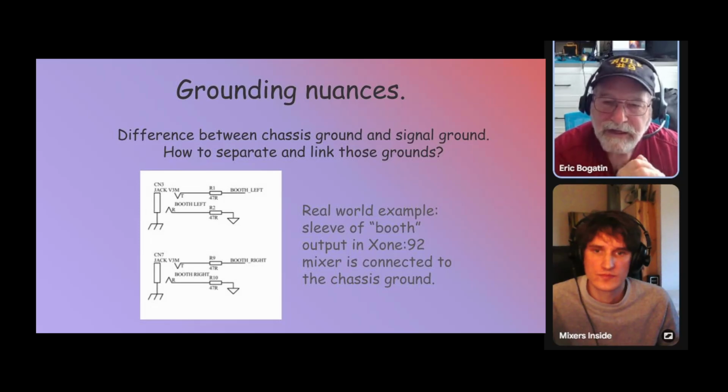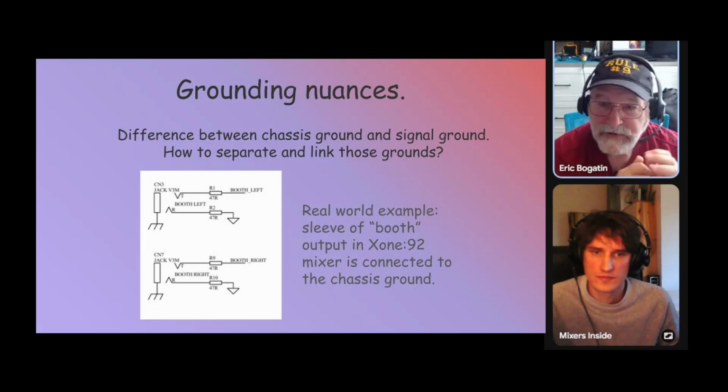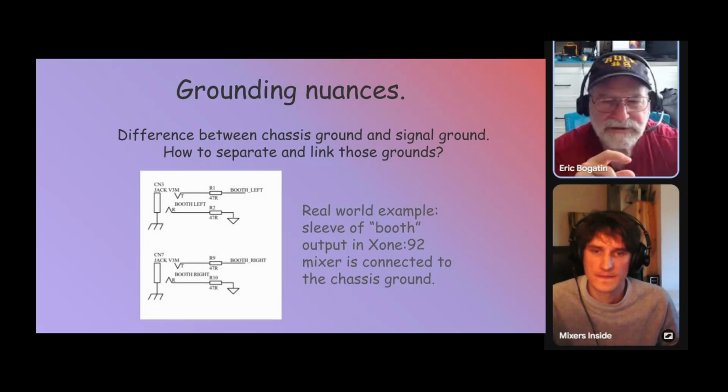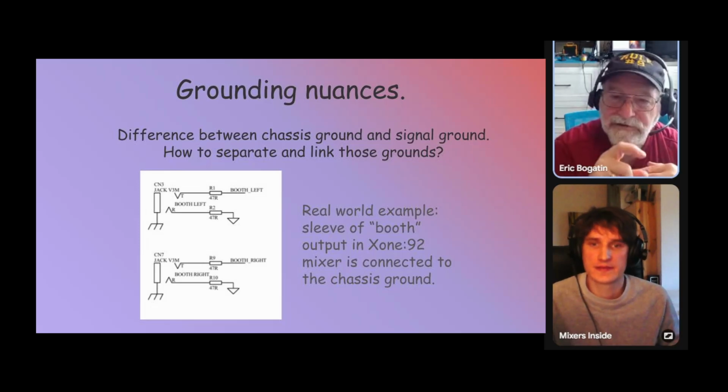That's your signal. If you pick that off as a differential signal and you connect the signal line back to your preamp and the return connection to the chassis back to your preamp, you still have a very good low-level signal. The low side of the preamp is going to be at the chassis voltage. If the chassis voltage goes up and down, that low side goes up and down, but so does the signal.